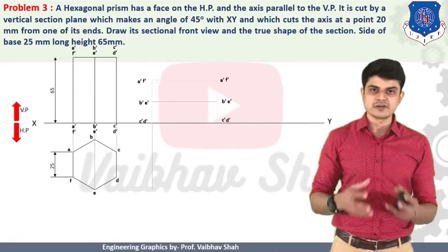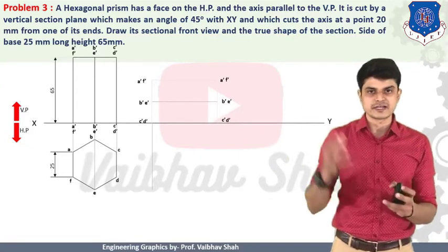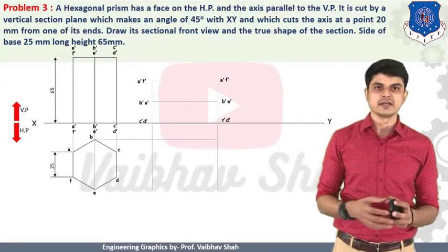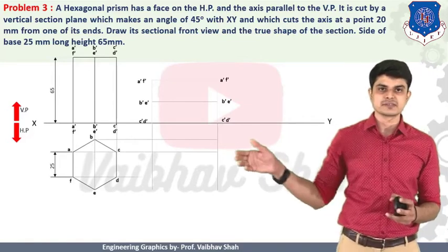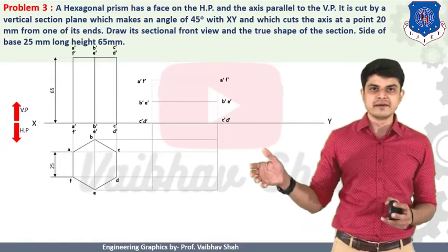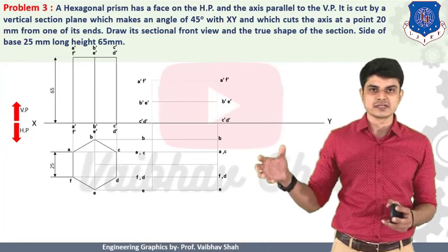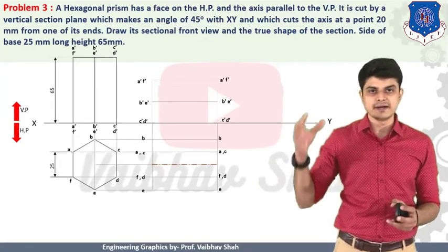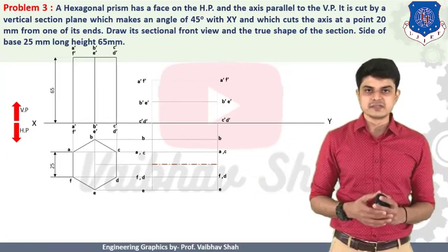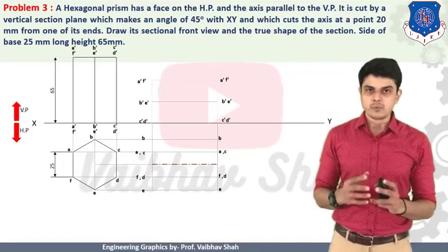After having this object, you should draw its top view. So let us draw vertical lines from each and every point, horizontal lines from your previously drawn image, and we will be having our final object generated, which is nothing but what? Your required hexagonal prism in the top view. Now, what we should do?